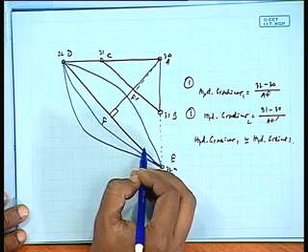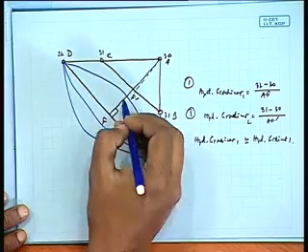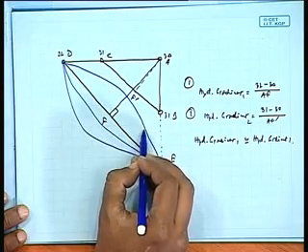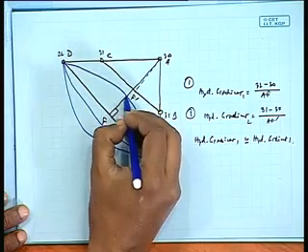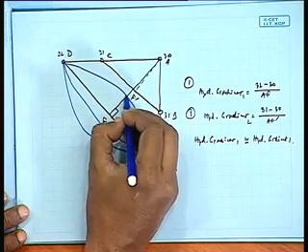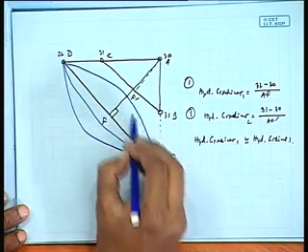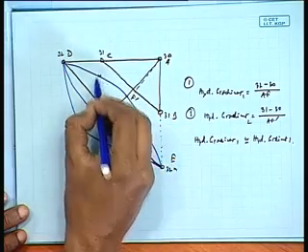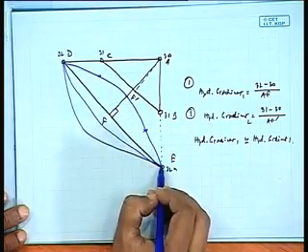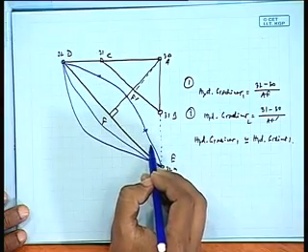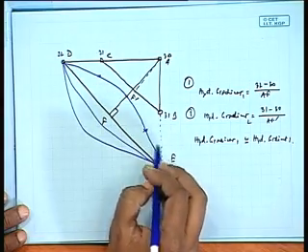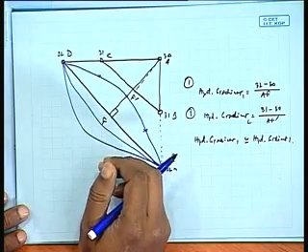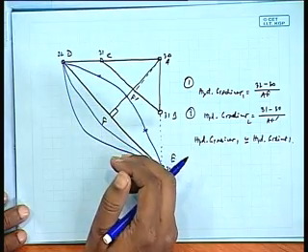So in such cases, we can find the equipotential line at different points. Say here there is one hydraulic gradient that you can see. You can find another hydraulic gradient here, and another here. So the average of that would be the hydraulic gradient of the field. This is called the hydraulic gradient of the field. This is how we can compute the hydraulic gradient.